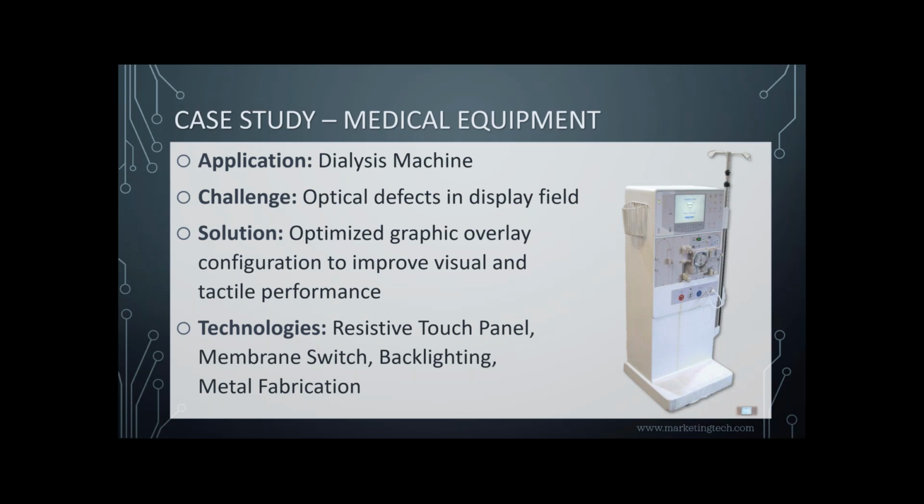And in the middle of the display screen, that was occurring. So we were able to mitigate through some dielectric dots, we would call them, some added processing to eliminate that effect. So this product can still engage a large resistive touch panel in this kind of environment.